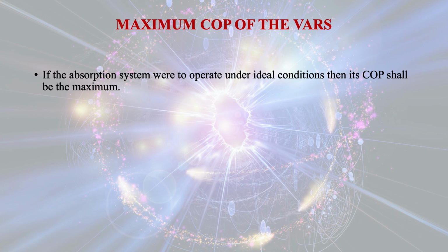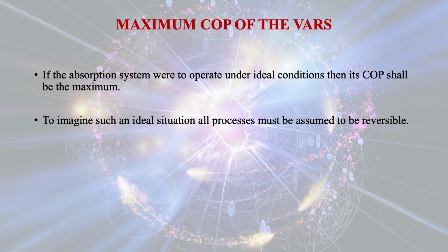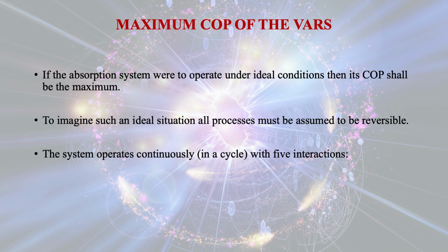Maximum COP of the VARS. If the absorption system were to operate under ideal conditions, then its COP shall be the maximum. To imagine such an ideal situation, all processes must be assumed to be reversible. The system operates continuously in a cycle with 5 interactions.